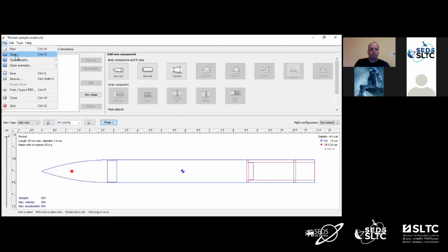And we've got our nose cone, we've got our body tube, we've got our motor mount all set up. Now, this rocket's going to have a problem. If you recall, we talked about in the first session, flight stability. We want to design the rocket so that it will fly straight just based on the shape of it. If it gets perturbed, hits a little air turbulence, it will actually correct itself and get back on track all by itself, just by the shape. And we said that compared to the center of gravity, we want to have the center of pressure behind the center of gravity. So in this case, on this design, we've got a problem.